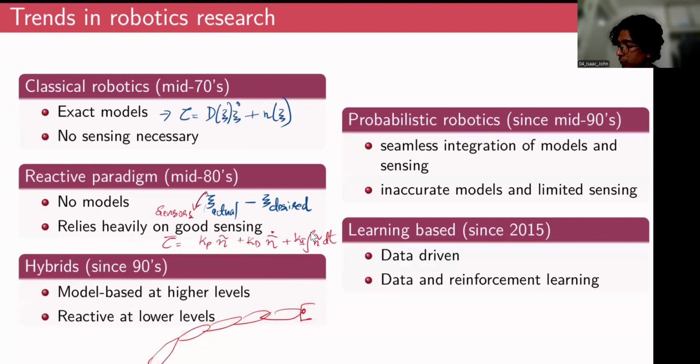We do that using the model information, purely using the inverse dynamics model, so that for a given trajectory for this end effector, we know what the trajectory should be for each of these joints. Once you have that information, you would use pure sensor feedback to estimate the control inputs, the torque necessary for the actuators.